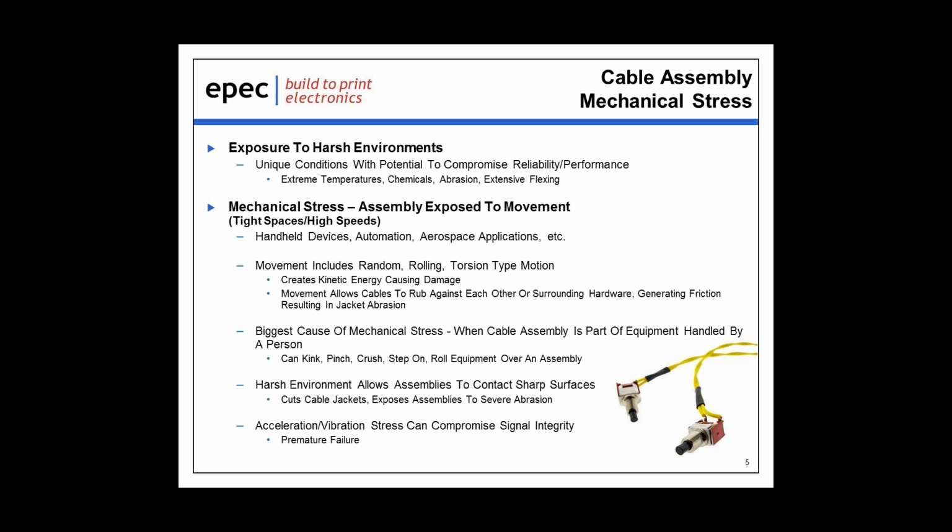People do have a tendency just to string assemblies out and not care whether they're stretched, pulled, or when they go to unplug, just grab the cable and yank on it, causing premature failure. Constant vibration or movement does cause jacket failure and does expose the components under the jacket to the outside environment, and again, causes premature or early failure.